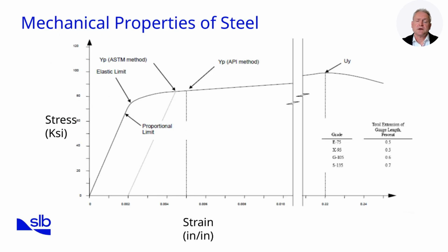The drill string is only as strong as the steel it is made from, so understanding mechanical properties is essential. Yield strength defines the point at which steel deforms permanently, while tensile strength represents the maximum load it can withstand before breaking. Toughness, or the ability to absorb energy without fracturing, is especially important under shock loading.